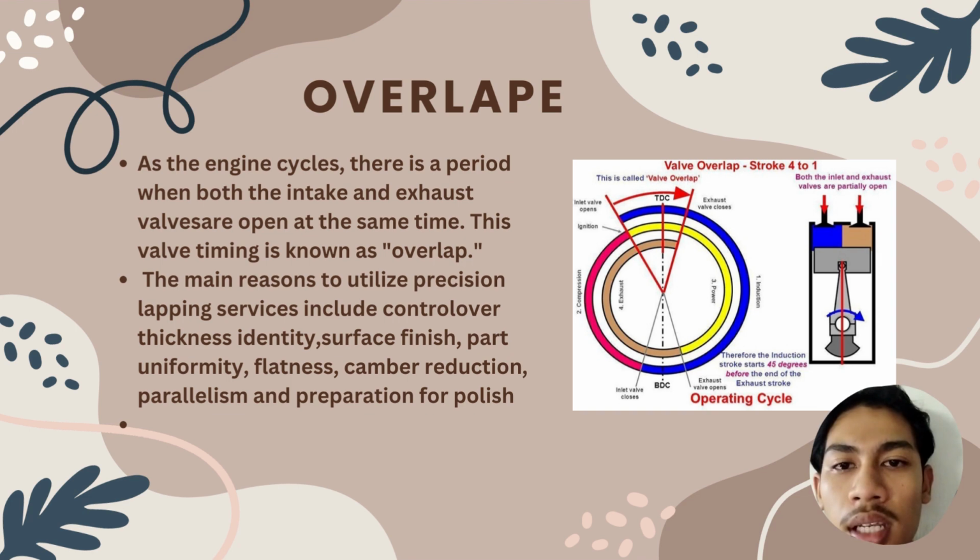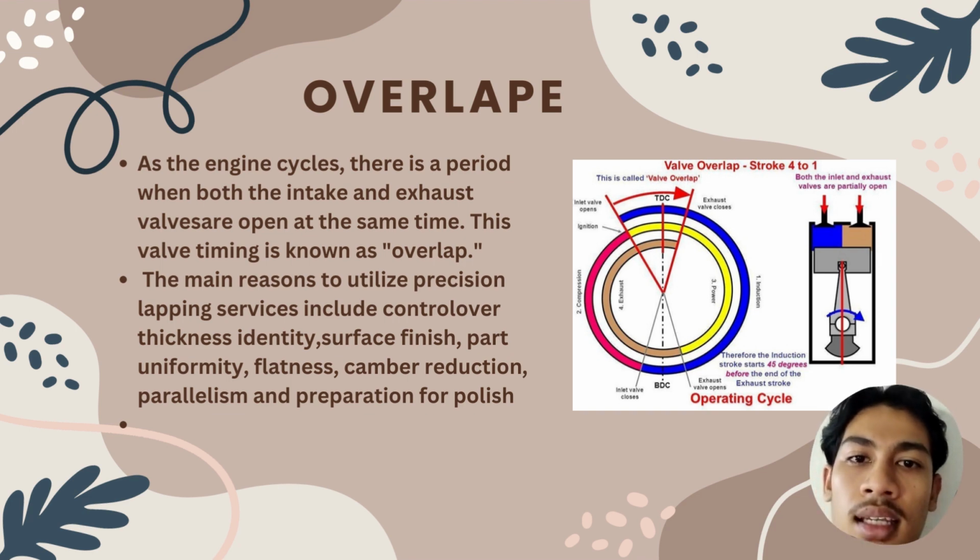Today I want to present about overlap in ICE. First point: in the engine cycle, there is a period when both the intake and exhaust valves are open at the same time. This valve timing is known as overlap.